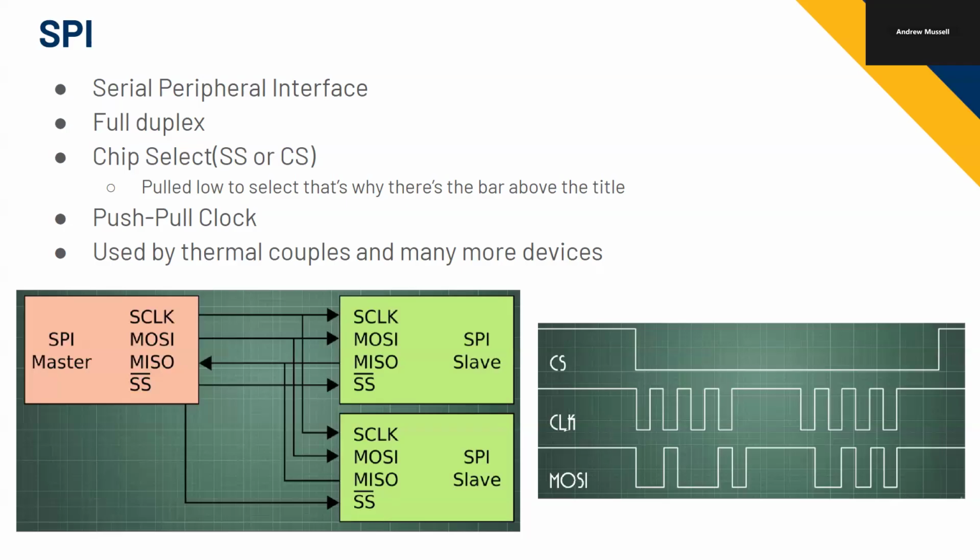Do that in the STM CubeIDE or something like that? Yeah, you would set up your SPI bus and define the pins in the CubeIDE. So is speed between SPI and I2C similar? No, SPI is usually much higher speed than I2C.